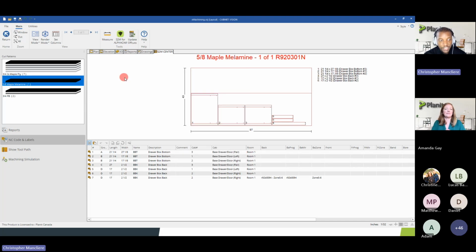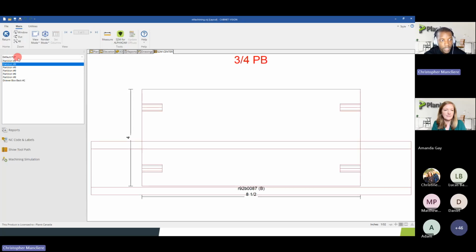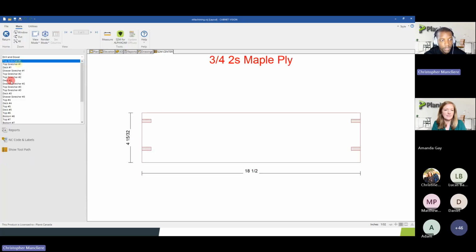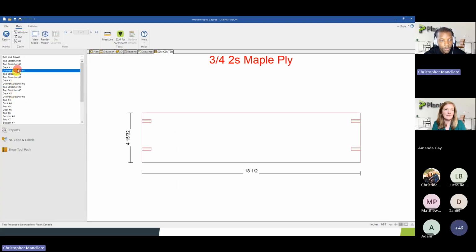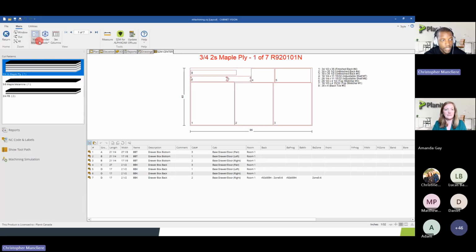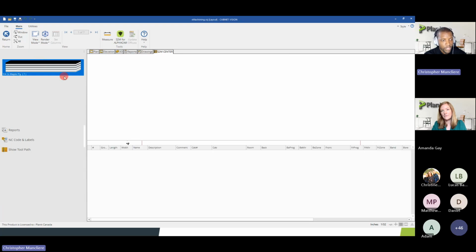And if you want to quickly see the parts, you can change in the view. You have a view button when you switch to part view, and you can see what parts go to the point-to-point. And in the drop-down list, you can see what parts go to the dowel machine. So for me, that's a good way to confirm what is going where. So I can see the entire workflow: nesting first, then in part view, I have some parts going to the point-to-point and some to the dowel machine to drill those dowels. So you can switch from pattern view to part view.